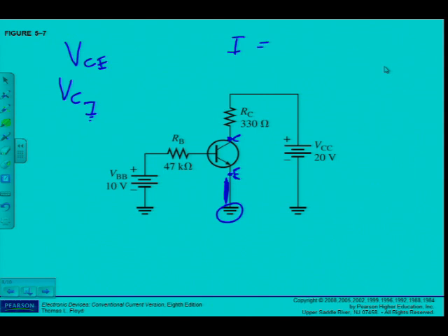Maximum current I is equal to V over R. Now I'm looking at maximum current, which in this case we'll call I sat, the saturation current. What is the maximum voltage? Remember, we're looking at this series part of the circuit, ne? What is the maximum voltage? It's my supply voltage, which is actually VCC.